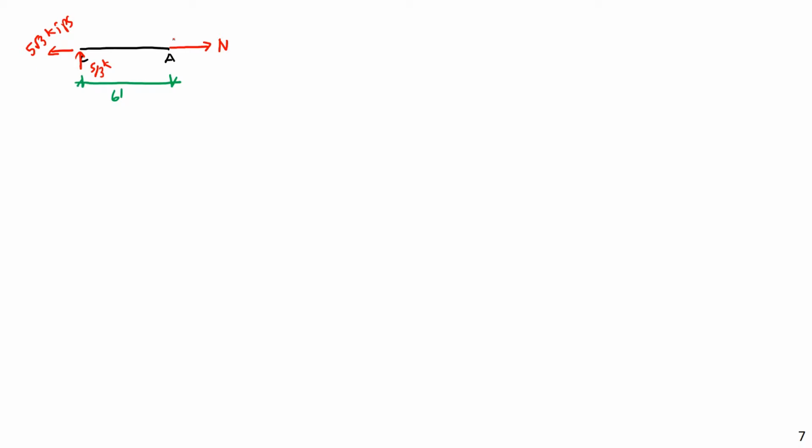So if I'm assuming positive initially, again, if I get a negative number, that's fine. And so I have a downward arrow here on the right-hand side, and I'm assuming a positive moment M. And often what I like to do when I'm doing method of sections like this, or working with internal forces, is put a subscript on each of these to indicate what point I'm actually making the cut at. So this is the free body diagram.